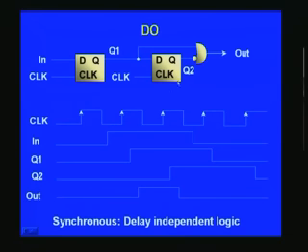So ultimately we get a pulse like this, and you notice that the actual width of this pulse is the width of one clock period. Except that there is a delay owing to the delay between clock and Q, because internally there are circuits, and any gate means a delay. That is what is getting reflected here finally, and this is how we solve for a single pulse if you desire just a single pulse to be created.